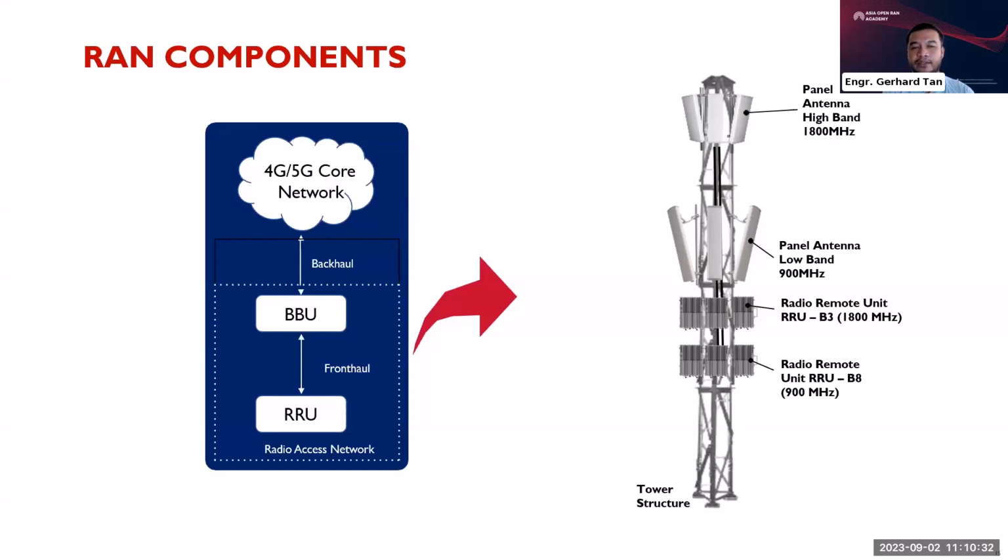That's why in those regions where it's the typhoon belt or wind loading is really high, the wind's so strong, then we have to build a self-supporting tower. Because in that way, you'll reinforce against the weight of the antenna, the wind loading, the stress and strain being experienced by the network elements, including the antenna and cable system, so it can withstand these loads that you're going to introduce.